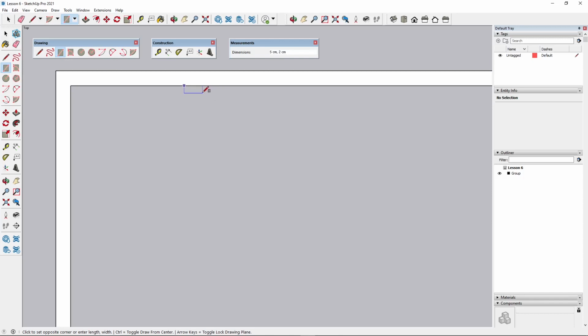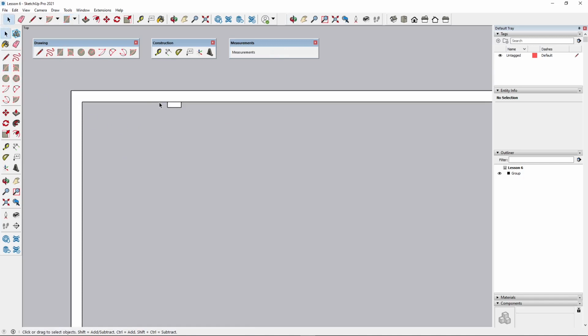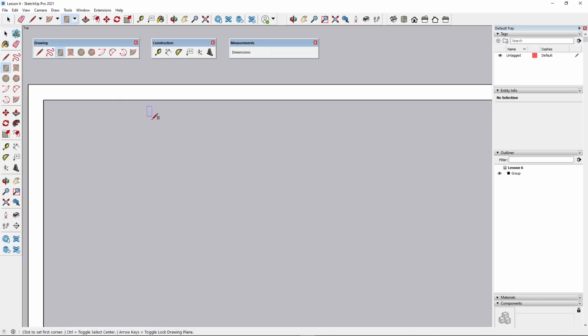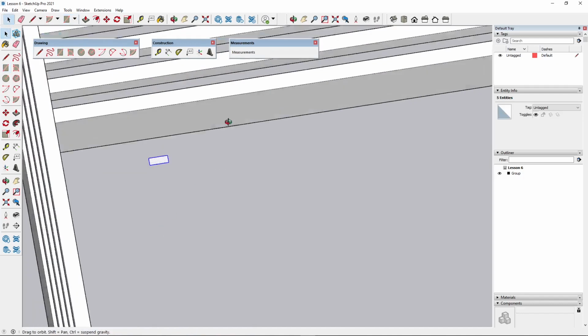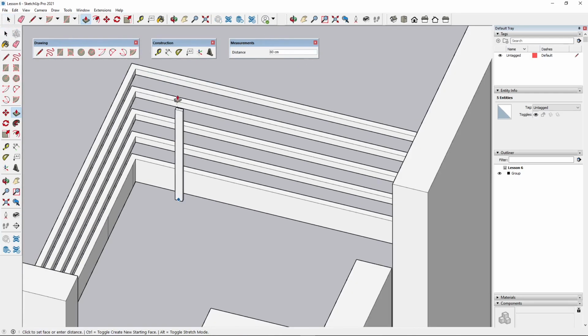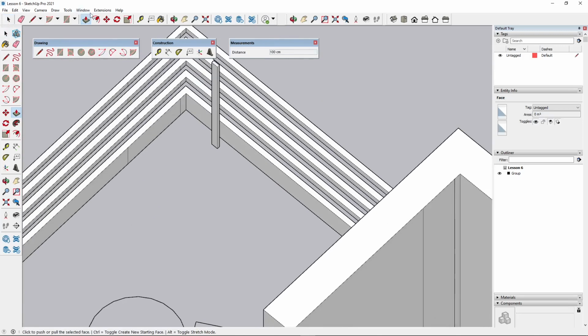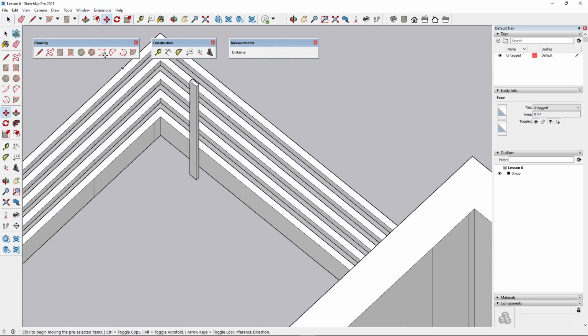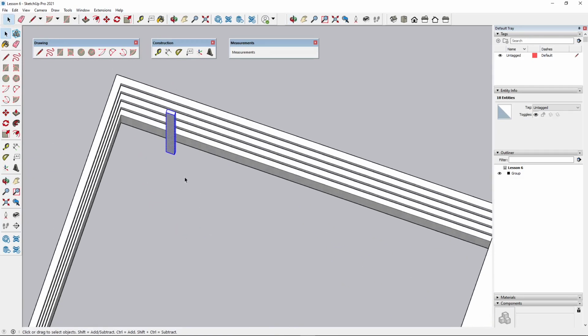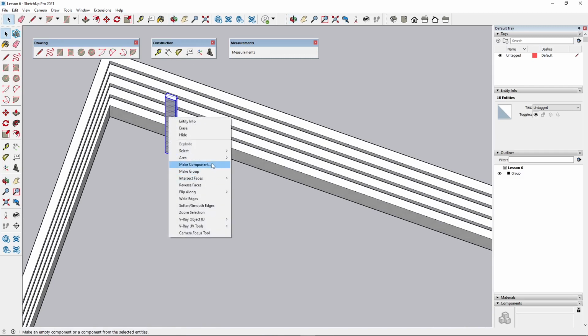So I'm gonna do this like 5 centimeters times 2 and go, well, I can do this attached already, or maybe it's even better if I do this separated and then attach it later on. So I can select it, and I'm gonna use the extrusion again, click, and then get that height, and now I will place it. Now before I place it, again, it's important that I create a group, otherwise it will weld with the rest of the architecture here.